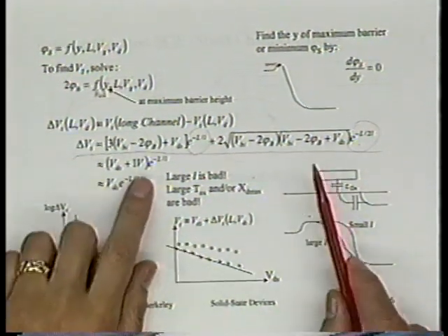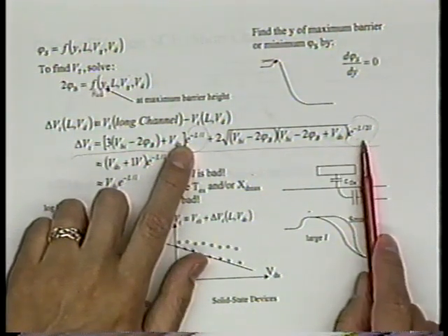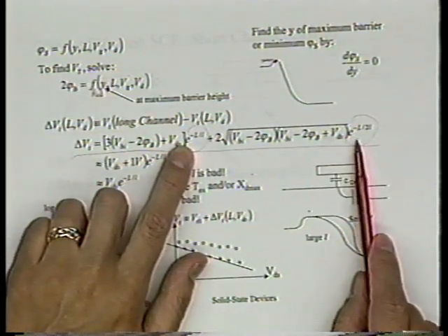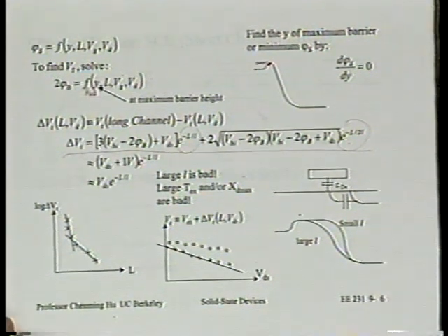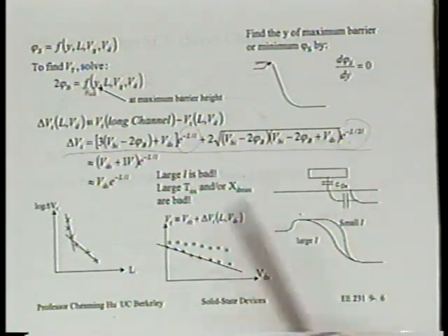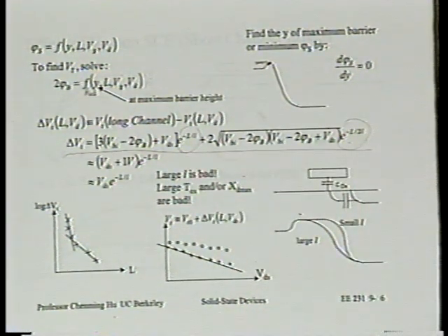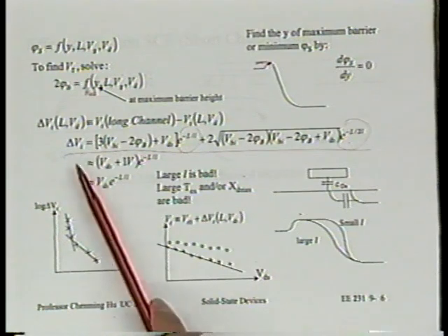So even BSIM3 used this exponential term. Now we have gone back to hyperbolic function of L. So when things like that happen, again, you have to believe the model is a pretty good physical model. Right? It's a pretty good model. That model is actually so good that this exponential approximation is just not as good for circuit simulation as going back to that.